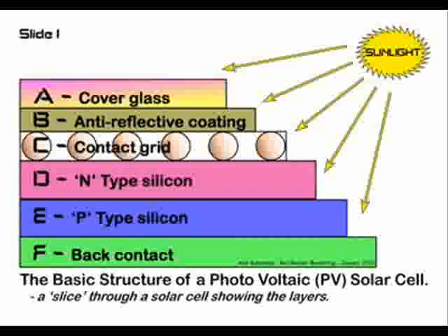We start with the electrical layer, which serves as an electrical contact and as a substrate to support the rest of the cell, which is often called a back electrode. A thin wafer of boron-doped p-type silicon is laid down. Phosphorus is then diffused into the top surface, forming a p-n junction very near the top. With the p-n junction near the top, most of the sunlight will easily reach the junction.